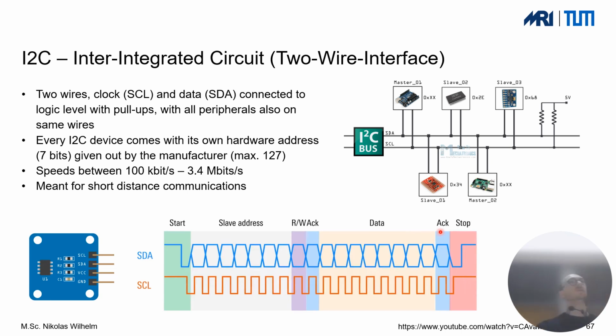And this can continue for a lot of time, but finally, once everything is happy, we can stop our signals again and pull them up to high again. So that's the basic idea. Only one slave can communicate at a time, right? But it's a very simple process because we only need 2 data lines and we can access as many simple sensors here as we want to.